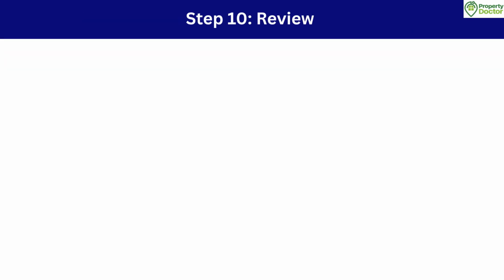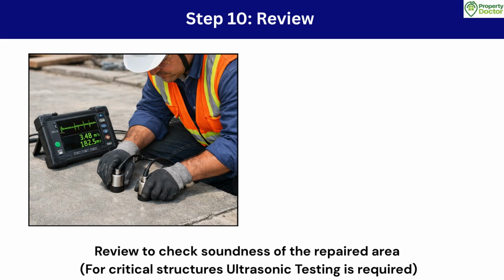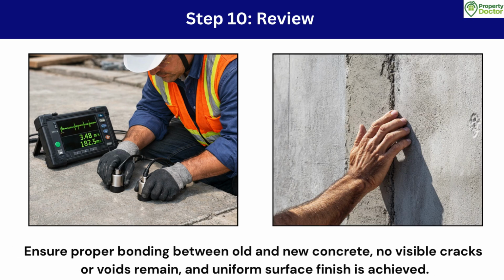Step 10. Review. Review to check soundness of the repaired area. For critical structures, ultrasonic testing is required. Ensure proper bonding between old and new concrete, look for no visible cracks or voids remain, and uniform surface finish is achieved.